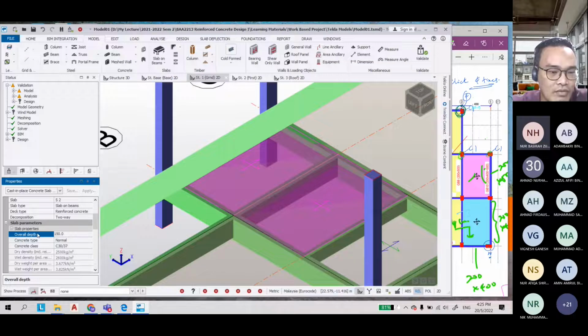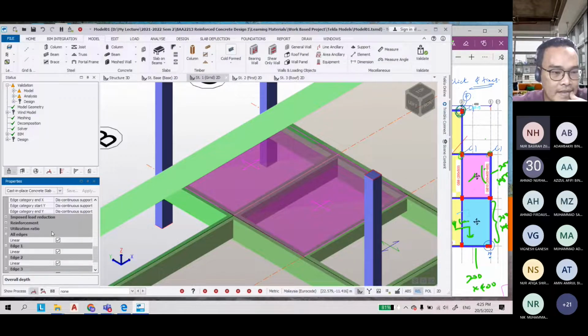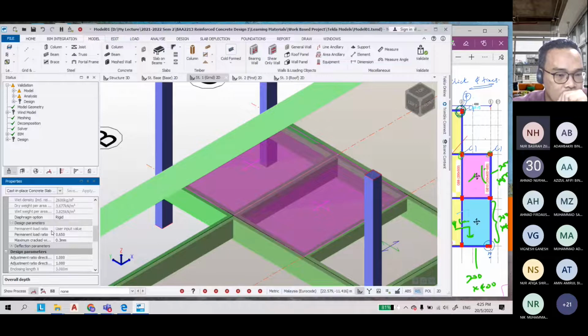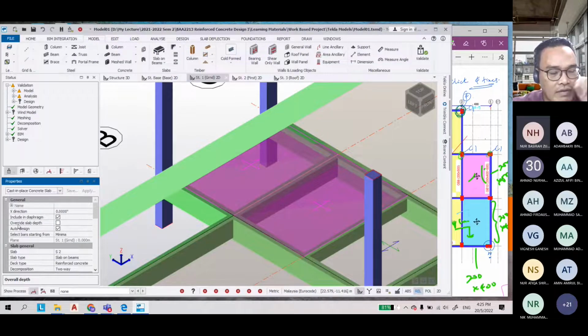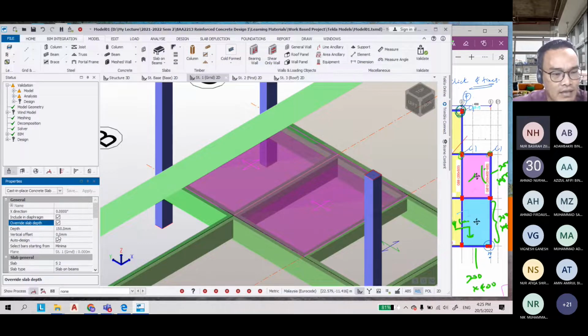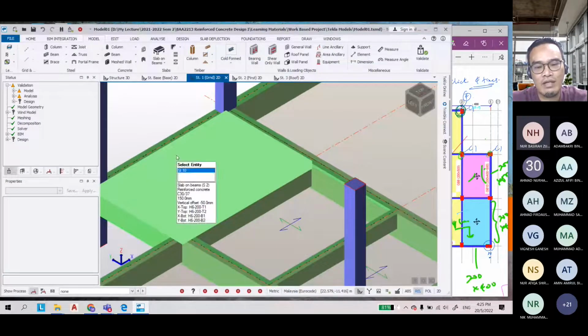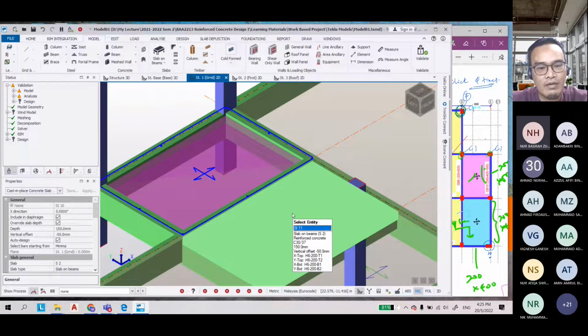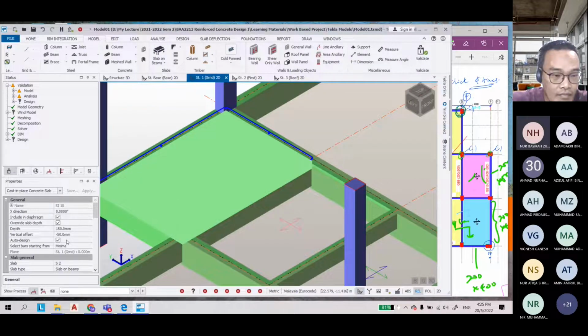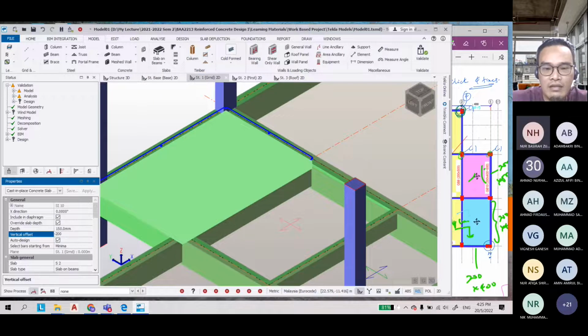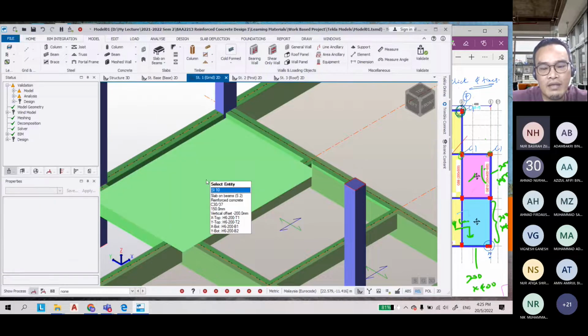And then okay, you click the overall depth here. Sorry, not the overall depth actually, it is here. Okay, override. Here, from number X direction, include in diaphragm, this one. Override slab depth. You click and then vertical offset, you make it as -50 and then you enter. So you can see that the slab is dropped now. Okay, maybe this is for toilet area, so it's dropped now. If you want the drop by, let's say 200, so make it as -200, so it will be deeper.